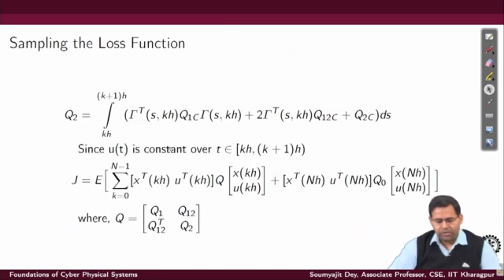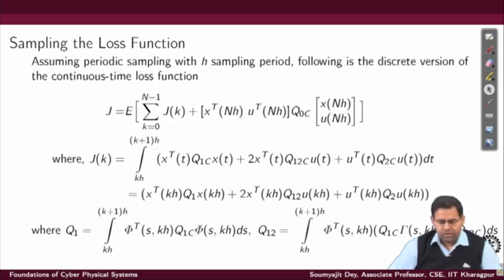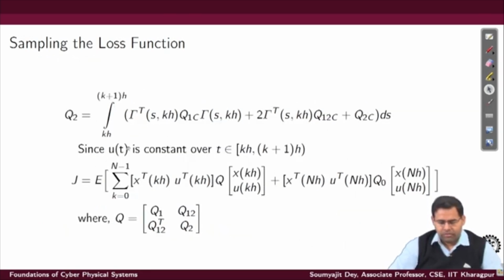Let us understand, of course, this conversion can be easily done through some standard tools that we have, and once this is done, the idea is that when we are doing this optimization in the discrete domain, then just like our older control designs, u is going to be constant over these intervals. So, I can just free the u when I am doing the integration inside this interval.